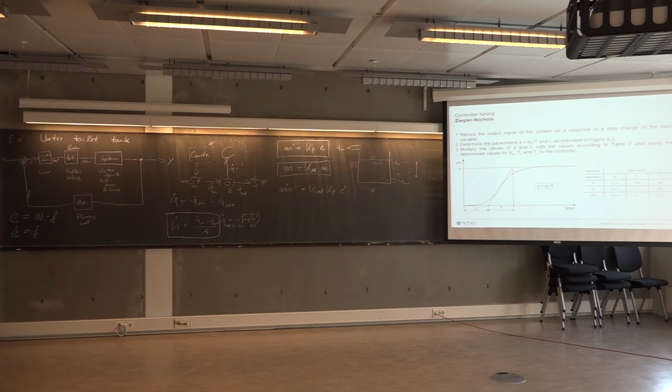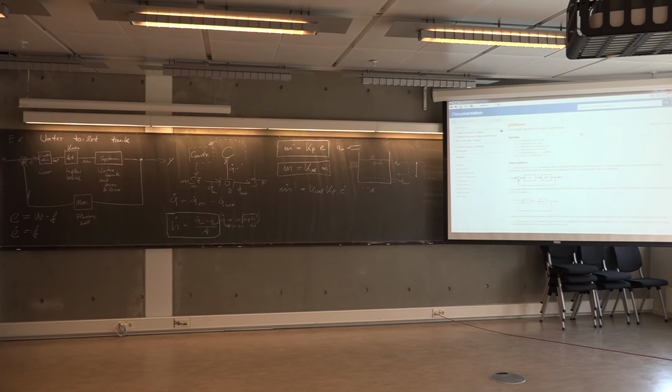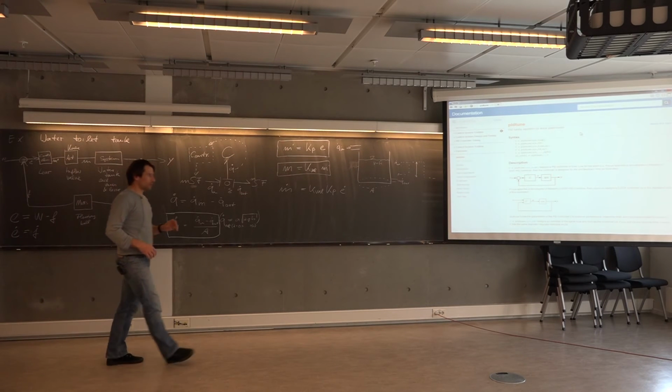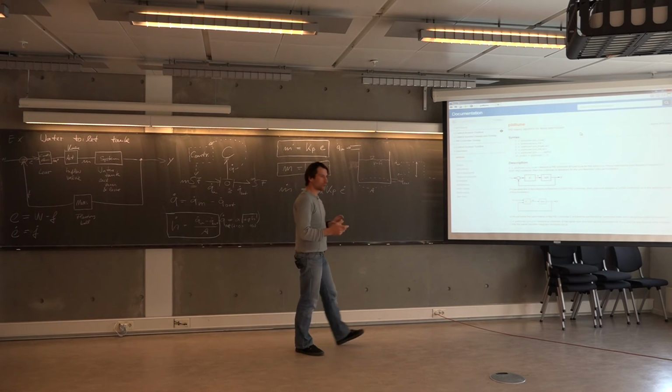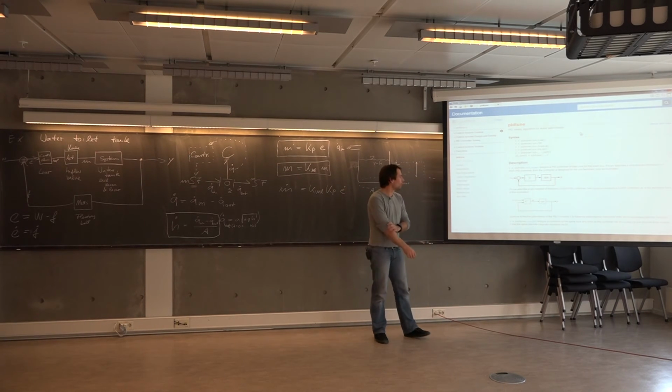If we take a look at Matlab, Matlab actually has quite some built-in functionalities. So there is, for instance, a function which is called pidtune, I think. Which helps you to basically tune the PID controller, assign certain numerical values for the individual constants in the equation.